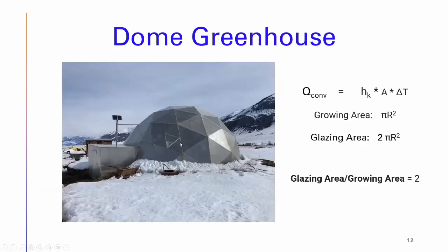Absolutely. So if you look at the dome, now these are flat surfaces. These aren't curved, so it was very easy to insulate that. I insulated that with 3 inches of polyisocyanurate insulation. The reason I used polyiso was because it has an R6 per inch. The glazing itself has an effective R value of 2.2. Now that is both convective and radiative. I want to be clear.